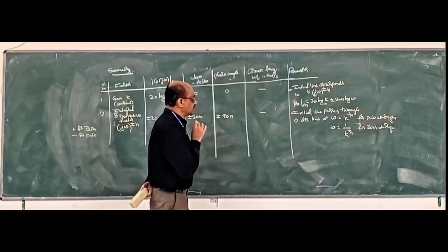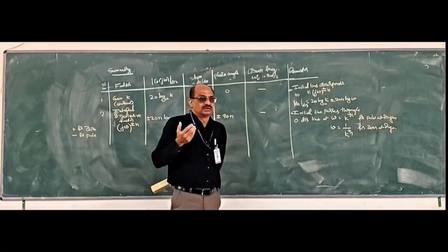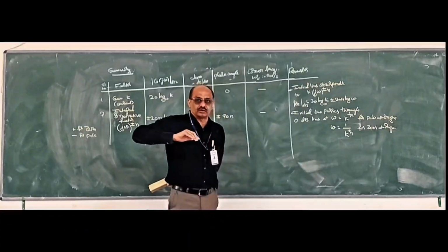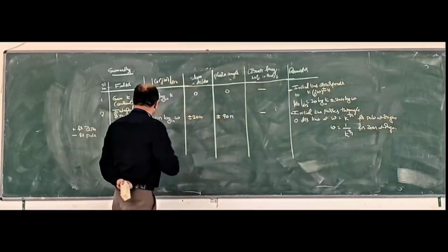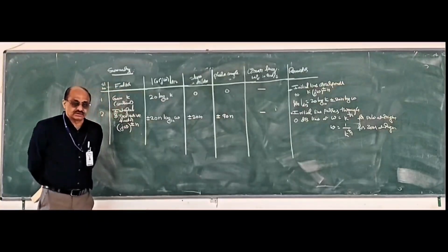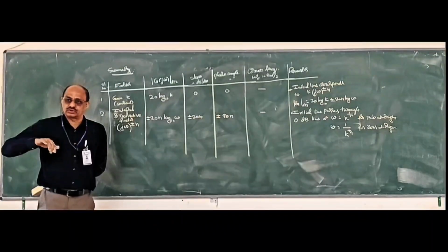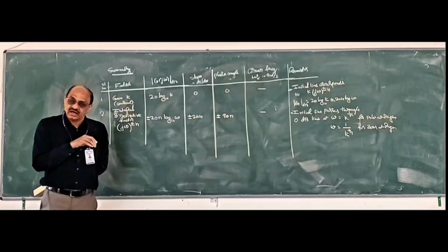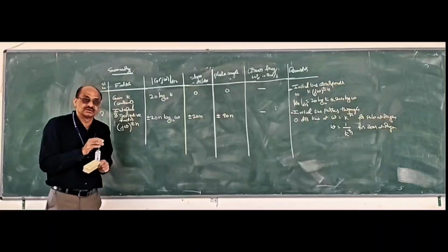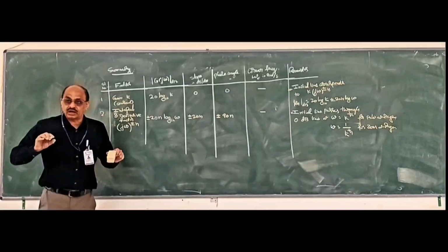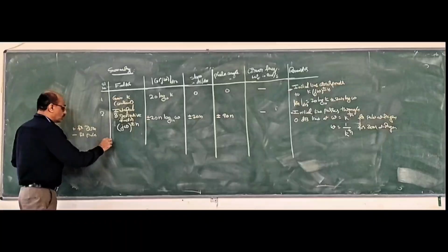Okay, we will start with the initial line. The initial line is always there because it doesn't have any 0 dB line. K and this pole at origin are 0, whereas the simple pole, simple zero or quadratic, they have two lines. But these two factors do not have two lines. So remember that, very, very crucial.